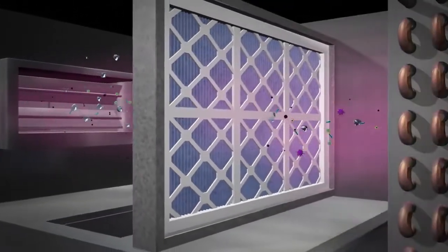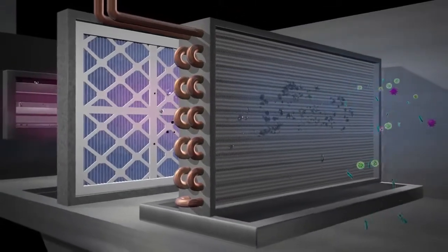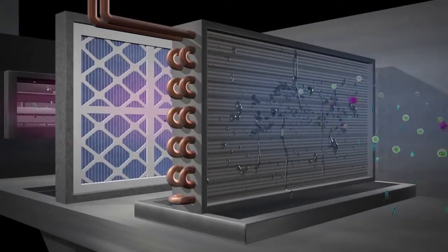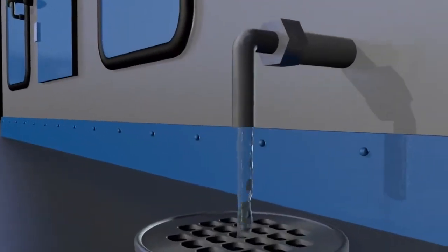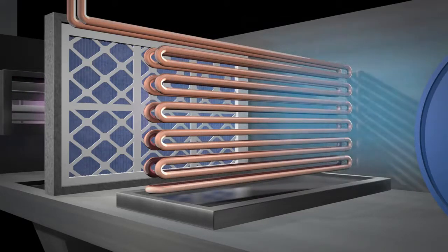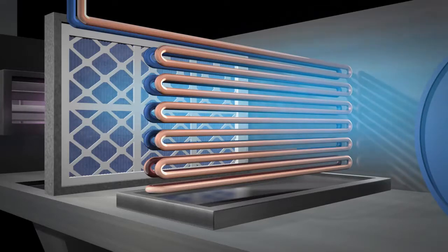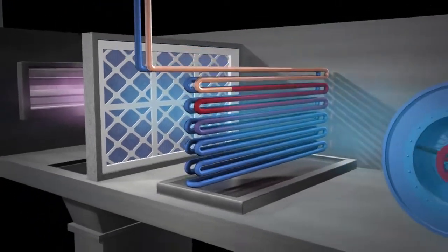This mixed air is passed through the primary filters to remove big dirt particulates. The resulting condensate in the cooling coil is drained away to the sewer. The heat from the building's air is absorbed through the coil fins by a cold liquid, typically chilled water, that is being pumped through the coil. The heat is then transported in the water back to the chiller.